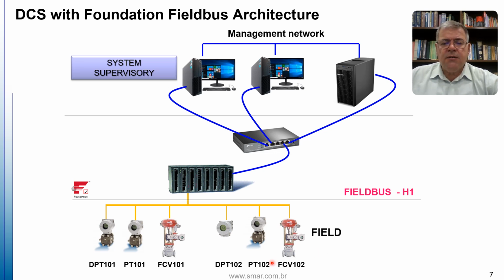It no longer sends the analog current signal of 4 to 20 milliamps. It transmits a completely digital signal. Each of these channels has the capacity to handle a maximum of 16 devices, ensuring efficiency. This is a significant advantage for saving on cable costs, installation savings, and design simplicity.